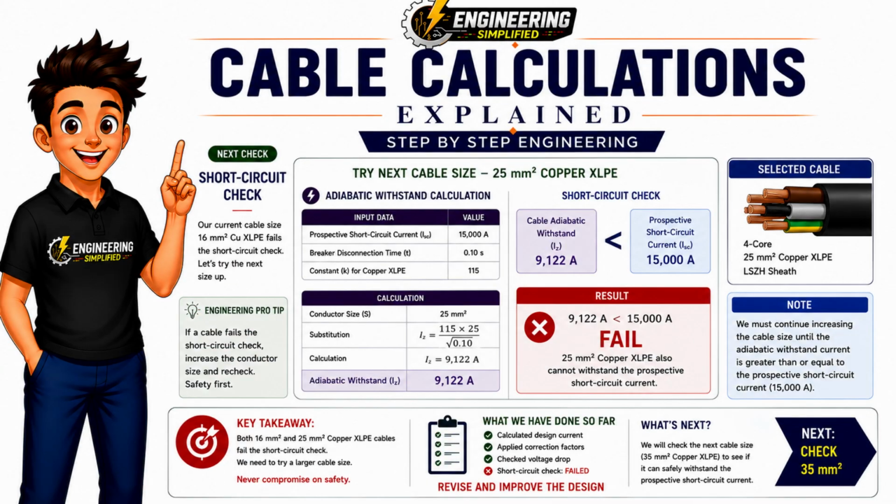Our first attempt at increasing the cable size is 25 square millimeters. Using exactly the same fault current and operating time, we repeat the adiabatic calculation. This gives a thermal withstand current of 9,122 amps. Unfortunately, that's still well below the required 15,000 amps, so the 25 square millimeter cable also fails the short-circuit check. Whenever a cable fails this calculation, the solution is simple. Increase the cable size and calculate again until the cable can safely withstand the fault current.